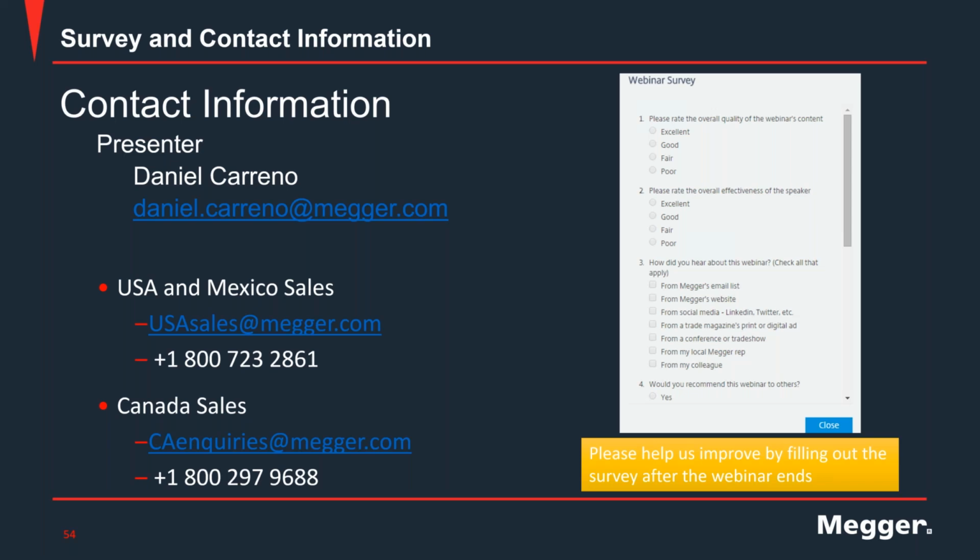All right. Also for you, Sanket, up to what percentage of error can we say that the readings are okay? What are the steps to be taken if error percentages cross that limit? So the same standard that I mentioned in the previous question, C57.12.00, states the tolerance for the ratio limits as 0.5%. That 0.5% is with respect to the nameplate values, and that's the default limit that's set in the software as well.